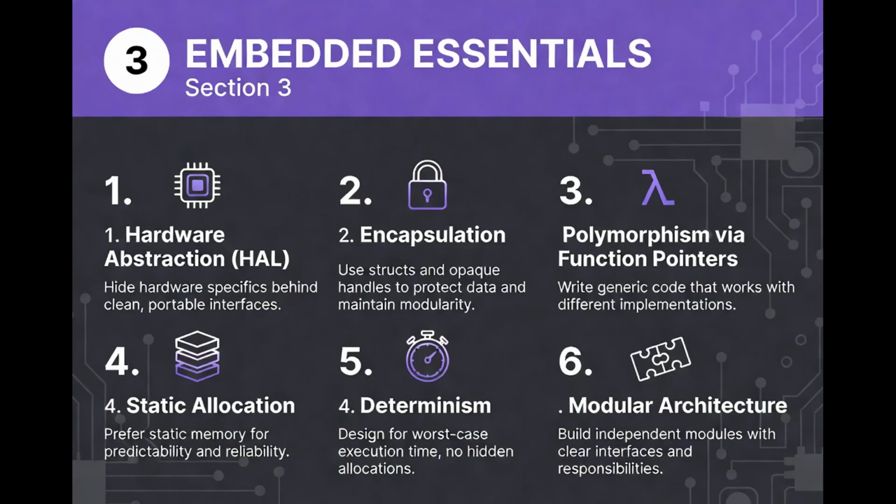Modular architecture is also one of the essential components of embedded systems. Large firmware systems must be modular. Each subsystem should own its own interfaces, hide internal details, and communicate clearly. Modularity allows parallel development, independent testing, and scalable maintenance.